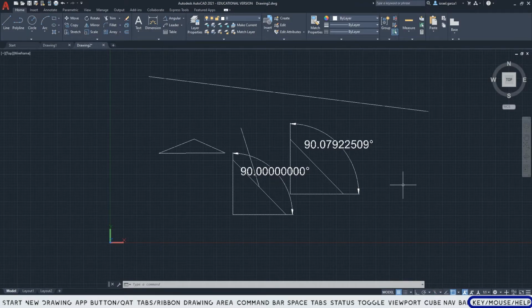Now I can draw a new line and slide my cursor along the line and find where it snaps to the node. There it is right there. You can see it looks a little bit like a crosshair. So now I can just click that where it snaps and finish my line. And I'll do it again at the other node.